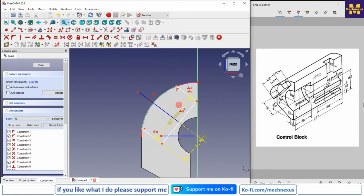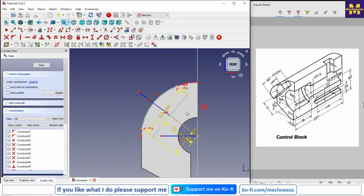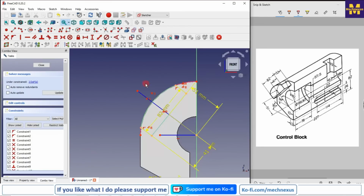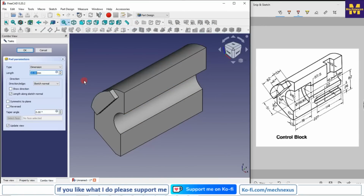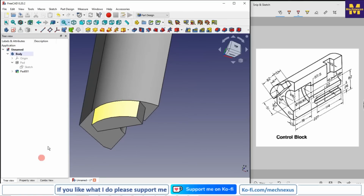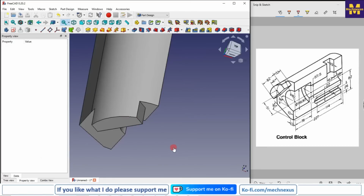And now from center to edge is 51, so I will select this point and this line and I will give it 51. So this is how this profile would be. I move the dimension outside for better visibility, and I will extrude it up to the distance 33. So I will close it and I will say extrude. I will give 33. Okay, so now I will refine it. So I will select this pocket, property view, refine through, so it will be merged.